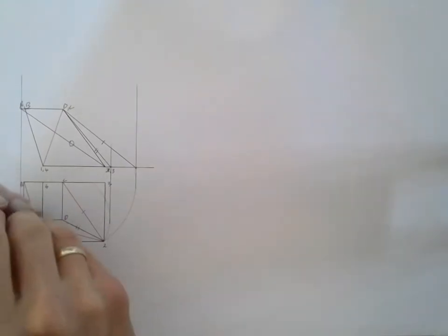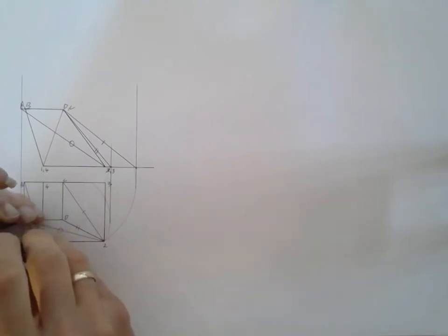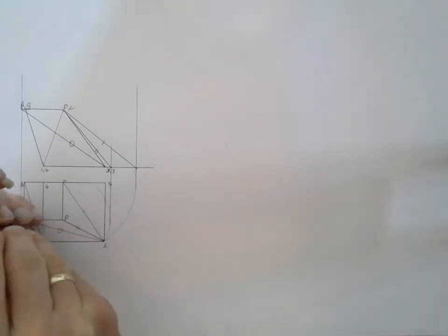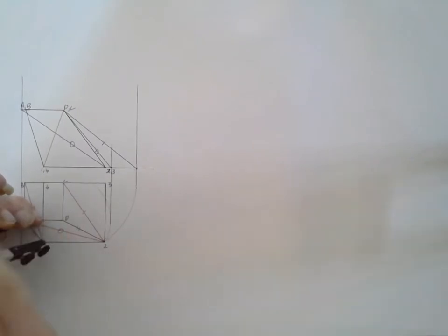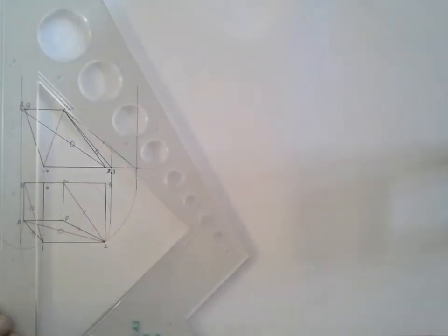Okay, next true length, moving on to line A1 over there. Again, my compass point, if I place it there and open it up to point 1, if I make an arc, that's going to fit in quite nicely. Just get it accurate. Okay, if I make an arc from there, it's going to fit in quite nicely if I take it to this side. So I'm going to arc out that way, and again project that line up into my front view.